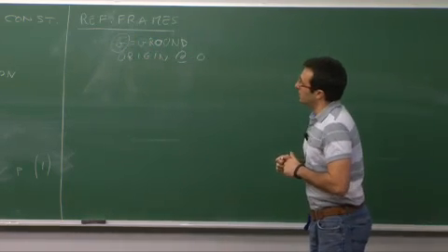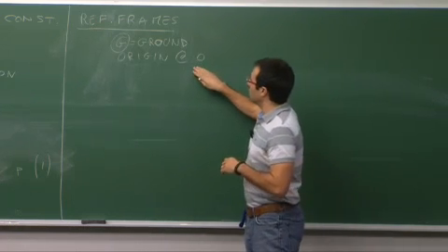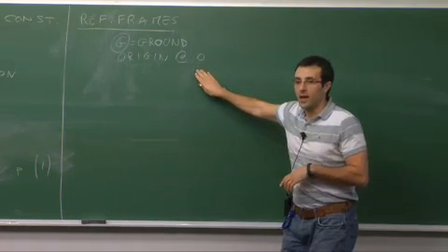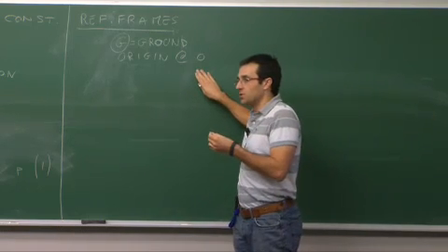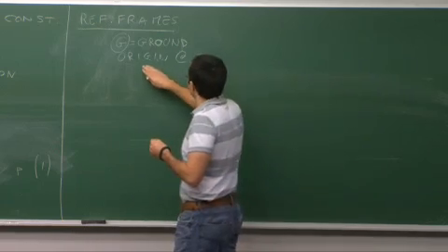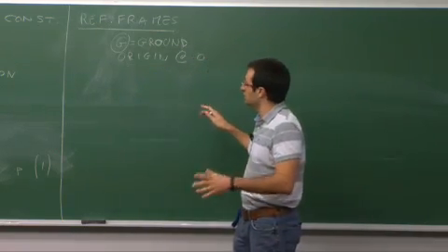And I'm going to measure things from that point because I have to write F equals MA, where A is seen by an observer fixed to the inertial reference frame. So I really need to be careful in choosing a point which is fixed in the inertial reference frame. Definitely need to do that.